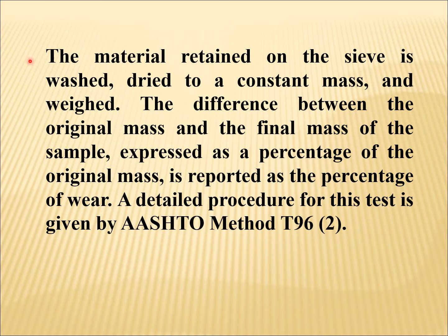The material retained on the sieve is washed, dried to a constant mass, and weighed. The difference between the original mass and the final mass of the sample, expressed as a percentage of the original mass, is reported as the percentage of wear. A detailed procedure for this test is given in AASHTO method T96.